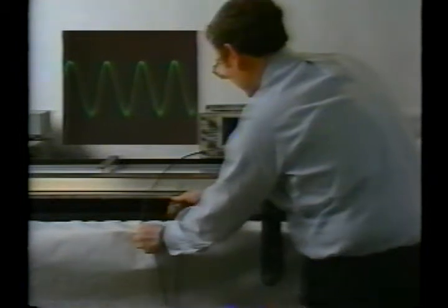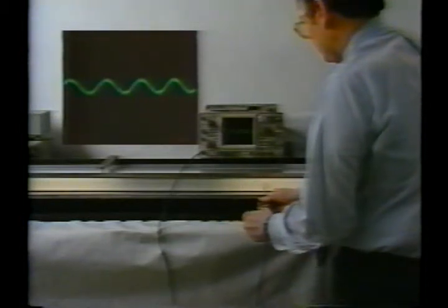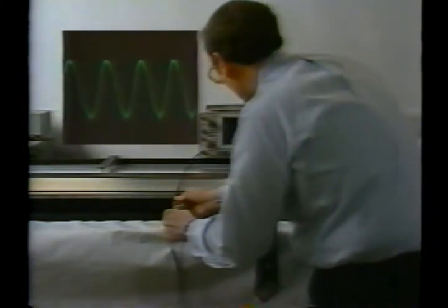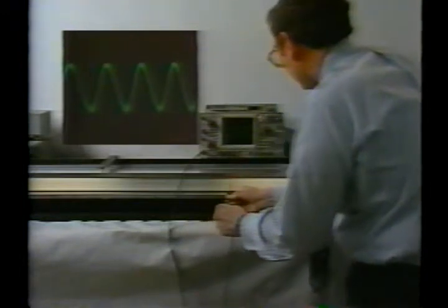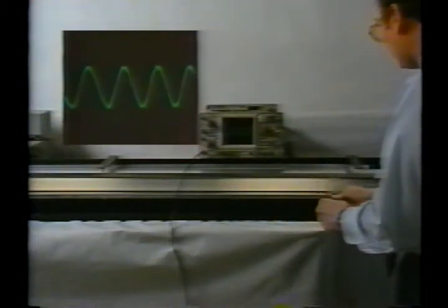Standing waves also result if the plates are open circuit at the right end. Now there can be no current in the y direction in the plates at the end, and hence no tangential z-directed magnetic field between the plates there. With the magnetic field zero at the right termination, the electric field there is a maximum. It should peak at the termination and at half wavelength intervals to the left of the termination.